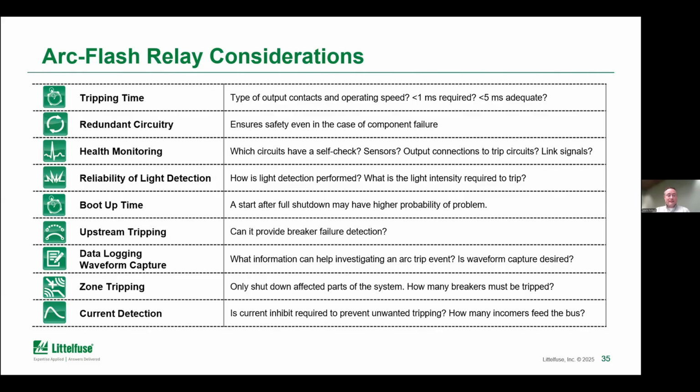The next one on the list here, I have health monitoring. Once you have this system installed and you have your light sensors, you want to make sure that this system is continually operating all the time, and that those sensors are being actively self-checked so that they're not in a situation where the cable becomes cut and the system is not alarming. So having some form of self-check on those sensors can be a pretty important item.